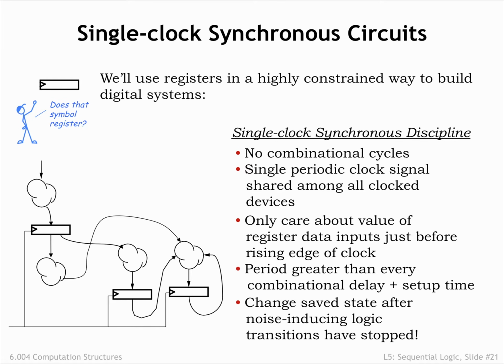A happy consequence of choosing the clock period in this way is that at the moment of the rising clock edge, there are no other noise-inducing logic transitions happening anywhere in the circuit, which means there should be no noise problems when we update the stored state of each register. Our next task is to learn how to analyze the timing of a single clock synchronous system.